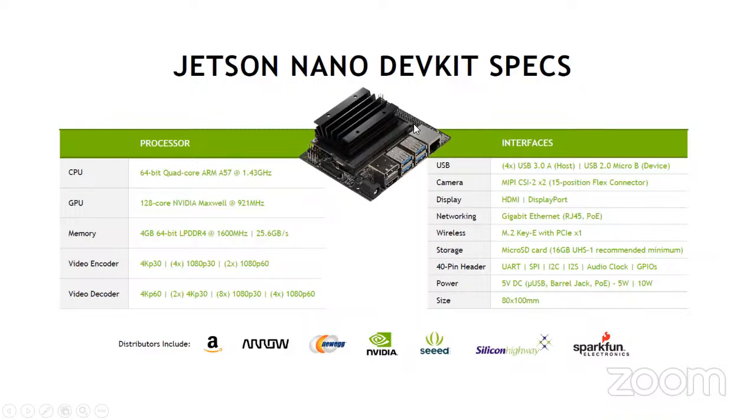If we can access through that communication port, we can access a terminal. You can use software like serial monitor software, different types of serial terminal software, or you can use PuTTY software to get access to the Jetson Nano. If you connect to that COM port in your laptop, you can access the Jetson Nano terminal.